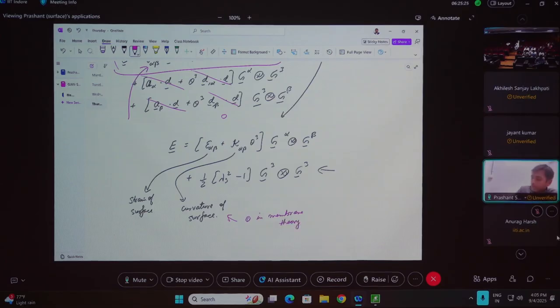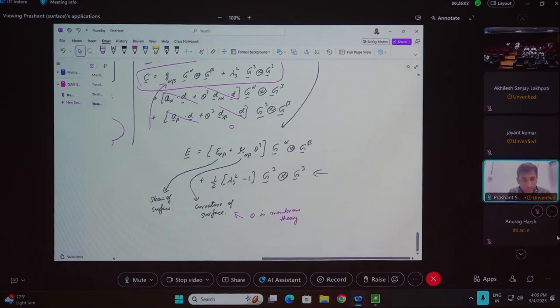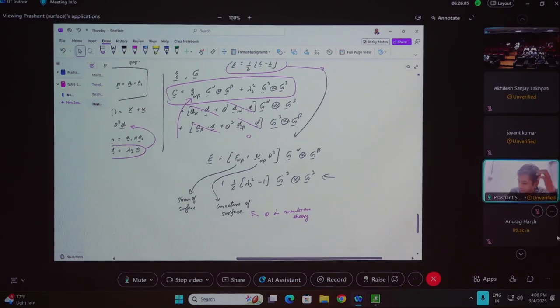You would not worry about what happens to the curvature because there is no bending stiffness. So for a shell, if you bend it, you need to apply forces, you need to store some energy. For a membrane, that doesn't happen. And then the rest of the process is pretty much similar in terms of writing down the energy, calculating the first variation, minimizing, and all that. All that process is the same. The main difference comes from here. Okay. So that's about the very basic, simplistic Kirchhoff-Love shell theory.